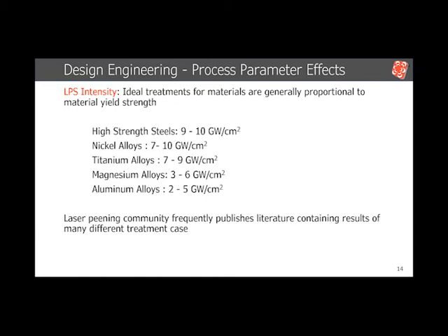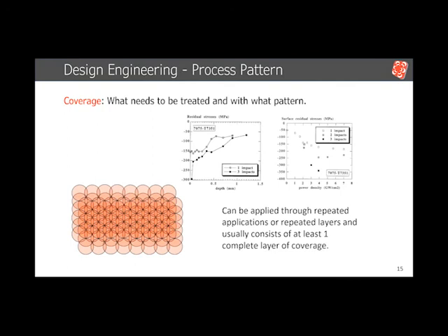These ranges help to guide what kind of power density you're going to use, but obviously the configuration and geometry of the part are going to play a very important role in determining what power density and process condition you're going to use. The other part that comes into play is what type of coverage, and we've talked about those as well, in terms of the placement of the spots or the pattern in order to cover the area to be processed. I think it was Stan who was showing 3 different versions of that. Michael may have covered that as well, at least 3 different types of patterns.